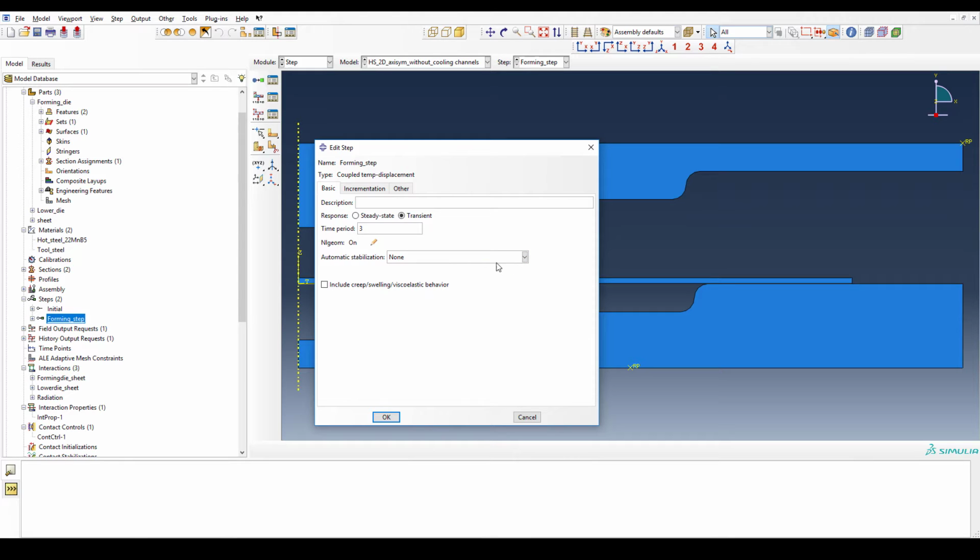This is the default one, and I have used it because I have seen it in some Abaqus videos or manuals, and it is a trick we can try if there are problems in our convergence, especially due to contact. We will see later in our results phase what problem I got and why I changed this. But the incrementation, the maximum increment, the number of increments, it's my wish.